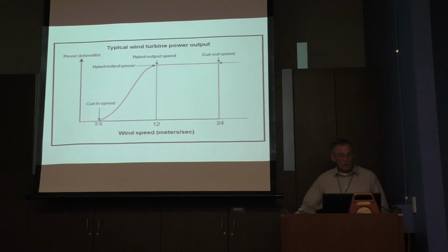Okay, and with regard to wind turbines, this graphic shows how wind turbines don't produce rated power until a sustained wind speed of 12 meters per second, or about 26 miles per hour, is achieved. And such sustained wind speeds are really uncommon in most areas of the United States. So not only is wind energy not suitable for baseload electrical demand, but its undependable speed in most U.S. locations also makes it unsuitable for matching peak electricity demand as well.